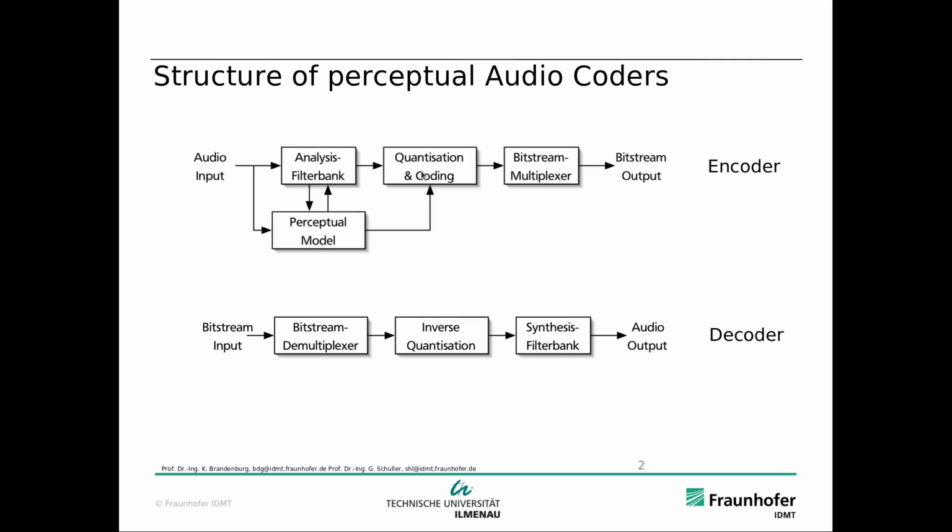Remember, when we make this quantization step size small, then we have a higher accuracy for the encoding, and we can reconstruct these components with this higher accuracy. So this would also cost more bits to represent it when we have smaller quantization step sizes. That means also we have more of those steps, and that means we need more bits to encode it. So that's bad because that increases our bit rate, right? So that's why we want to make those quantization steps as big as possible, such that we have shorter code words, which saves us bit rate.